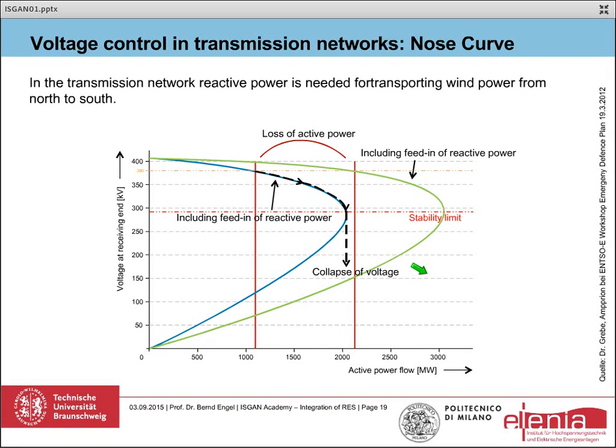In the transmission grid, we have sometimes the need for capacitive behavior of the generation because of this nose curve.